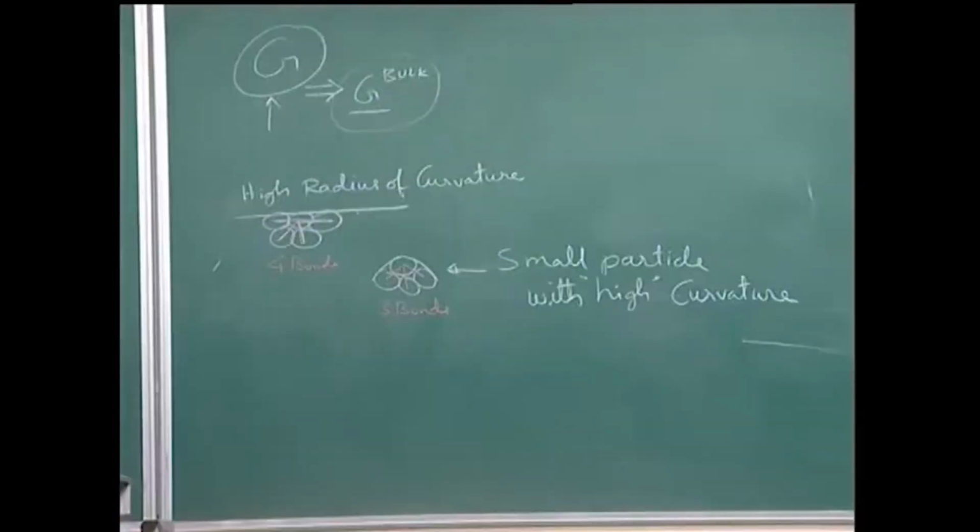So, just to summarize this slide, curvature plays a very important role in nanomaterials and nanocrystals and nanoparticles, unlike the case of the bulk materials, where I can describe the system by a quantity which is the Gibbs free energy, which is not geometry or size dependent. When you come to smaller and smaller particles, because of this effect of actually unsatisfied bonds, there is an excess energy over and above the bulk energy, and therefore, these particles are in some sense more unstable as compared to the bulk material, and we have already seen the consequence of that, they are very reactive. And we will take up one specific example of these kind of curvature effects in a phenomenon known as coarsening of precipitates.